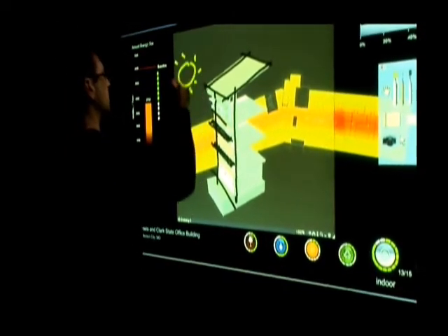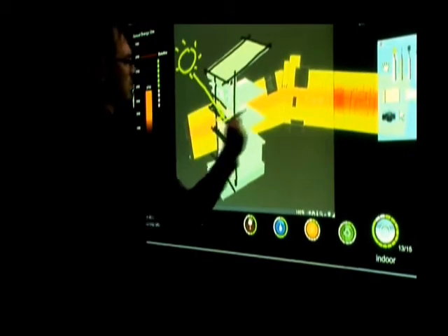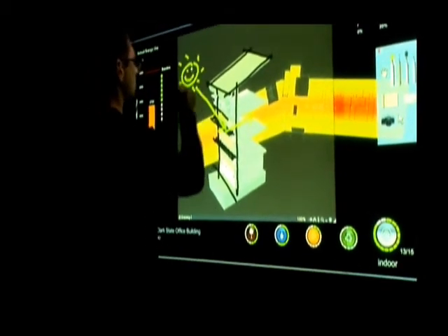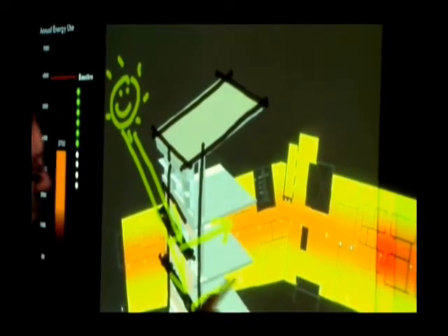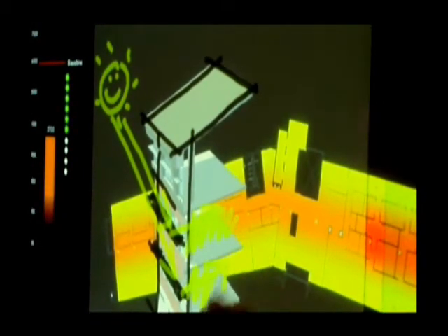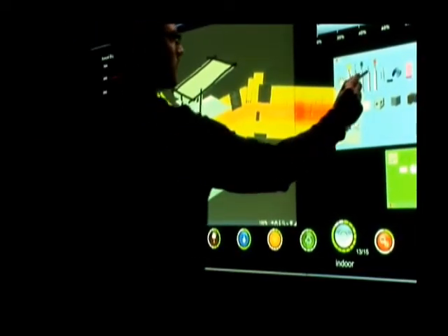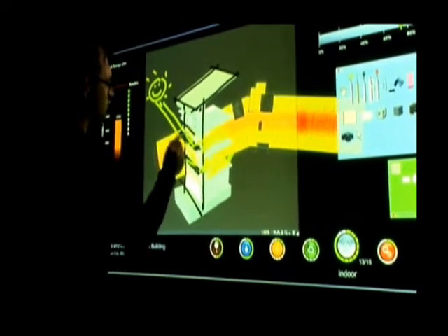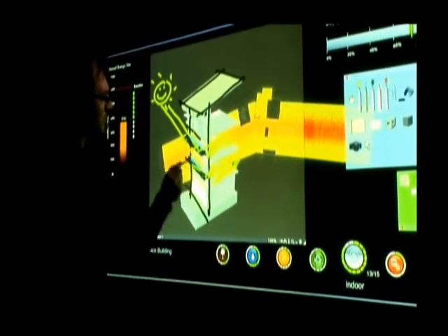Horizontal and vertical louvers are added to the model, reducing total energy consumption while maintaining the 2 daylighting credits. To further improve energy efficiency, the designer experiments with glazing alternatives, such as low-E glass for the south facade.